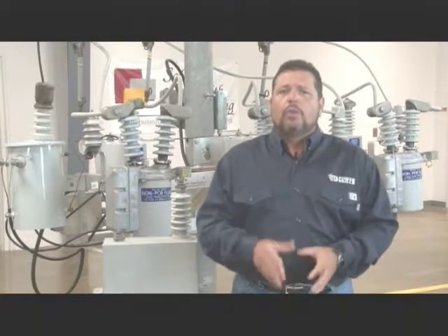Well, we've just seen how capacitors can be used to improve the efficiency of a distribution feeder. We looked at the basic parts of a capacitor: two parallel metallic plates separated by an insulating medium. And we discussed the three characteristics that determine a capacitor's ability to store a charge: size, closeness of the plates, and insulating medium. We also discussed power factor, which is the ratio of useful working power in kilowatts compared to the total power in kilovolt amperes supplied to the circuit.